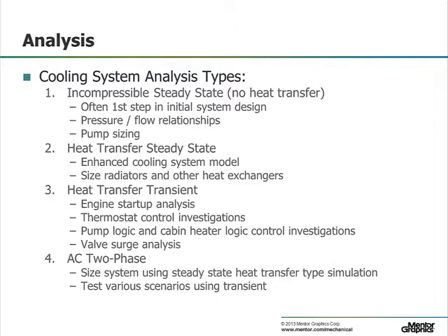Next, the designer may add in heat transfer. This way, the variations in fluid properties due to changing temperature could be considered, as well as frictional heating in the loss components. More importantly, different heat exchangers can be tried to see what would be the impact on top tank temperature. Here's where a lot of cooling system analyses end, though at times engineers will investigate transient behavior, especially when analyzing thermostat controls to check one thermostat versus another.